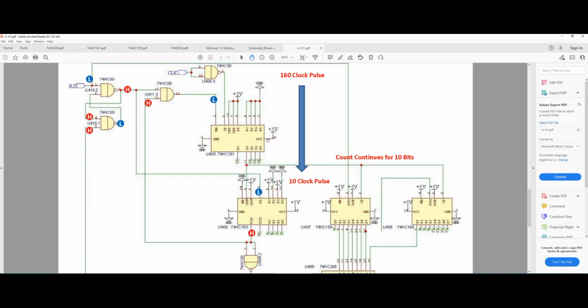So as you can see, this chip will actually only be outputting 10 clock pulses. The reason is that this chip will be counting down all the time when it is active. And therefore, once this reaches 0, essentially it shuts down the upper circuit, right? But we still generated 10 clock pulses, and that's all we need.